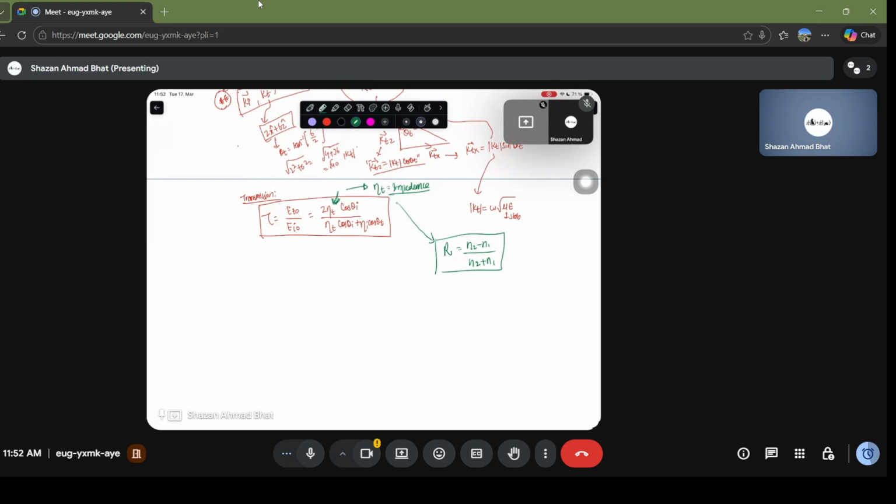Okay, so now if you want to find one of these, you can solve for it, and accordingly, if you want to find the magnetic field component in the transmitted wave also, then you can find it using its wave vector, transmitted electric field divided by eta transmitted. So how much is basically going in? This controls the direction, this controls the amplitude, and this controls how much is basically going inside it.